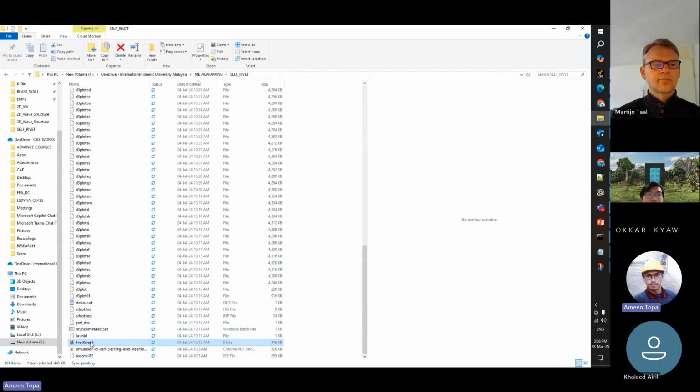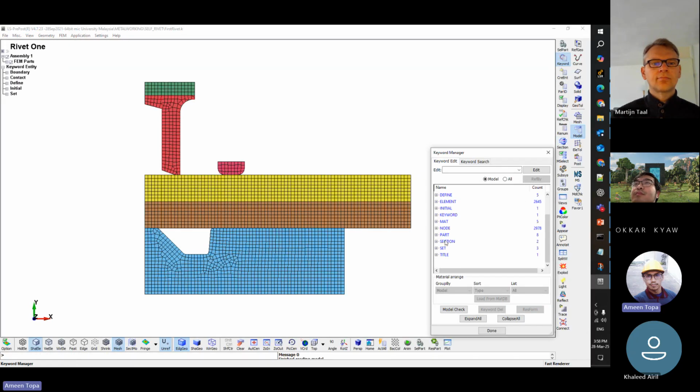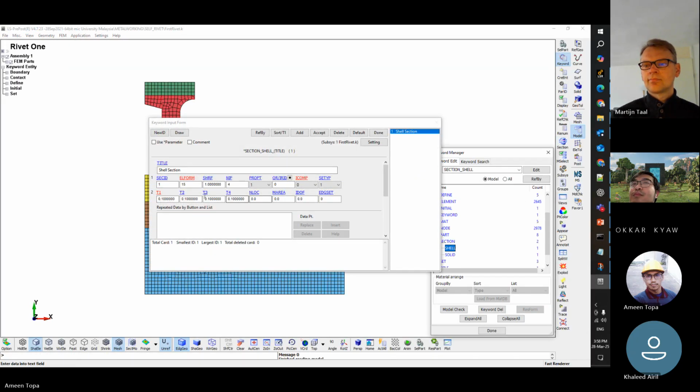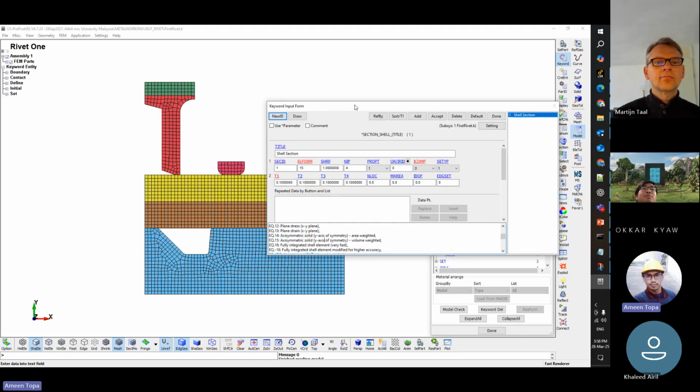What sort of element formulation did we use? Here, I use 15. It's axisymmetric solid. If you use this one, then you are modeling half of the tooth, with the assumption that the tooth is perfectly circular. That's the meaning of axisymmetric.